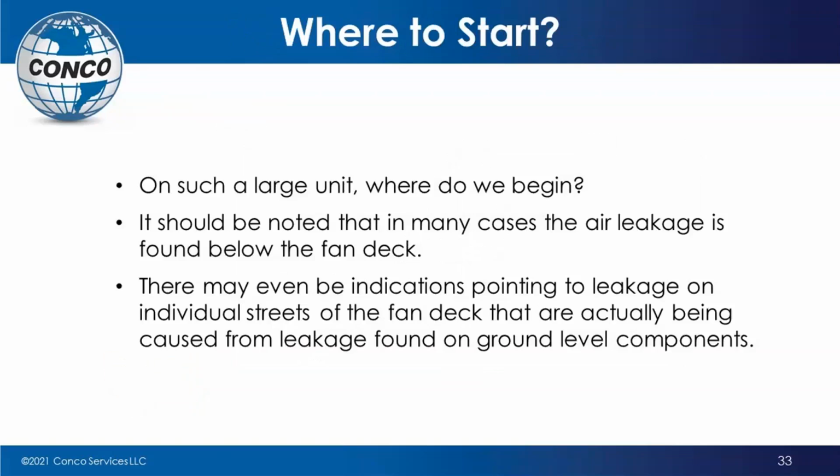Well, first thing is you've got to have an experienced technician. An experienced technician is going to come in, and he's going to start asking you questions. And as he asks you questions, that's going to pinpoint to him some ideas on where to begin. But we find in a lot of instances that the air in-leakage is actually found below the fan deck.